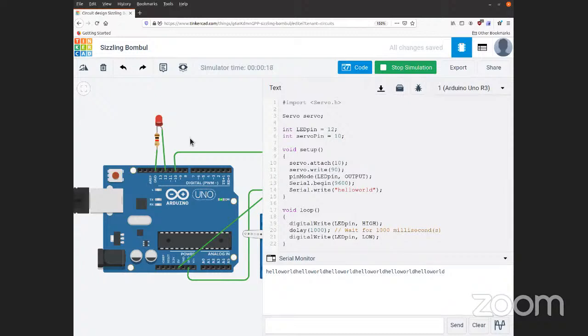So you're always doing high, wait a second, low, high, wait a second, low, high. And so that low-high, if you had an instrument, an oscilloscope, you could see that LED actually turn off for a very small amount of time, the time it takes to process the digital write, maybe nanoseconds. But to the human eye, you're not going to see that. So it looks like it's on all the time. So make sure you put your delay after each line. You don't forget that you need that pause after both transitions.